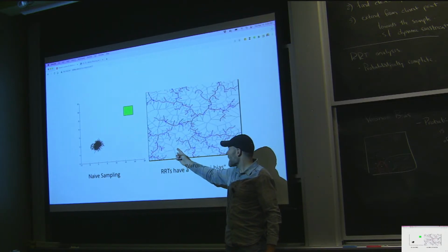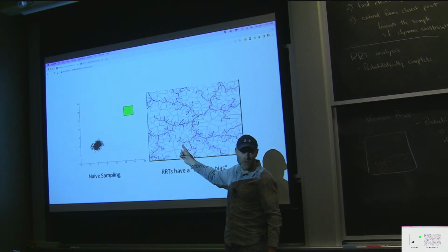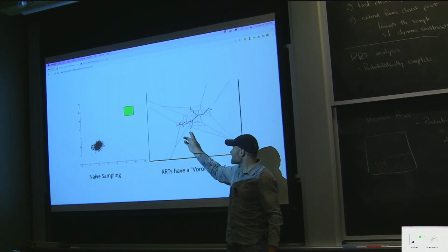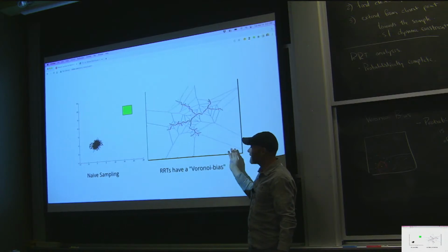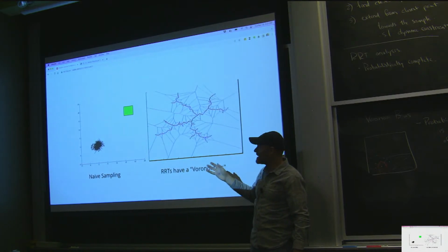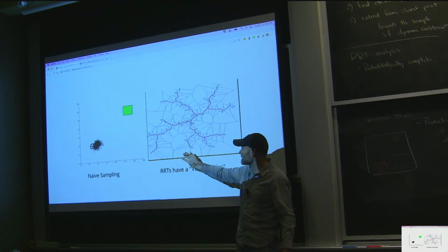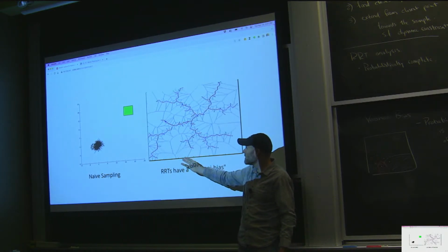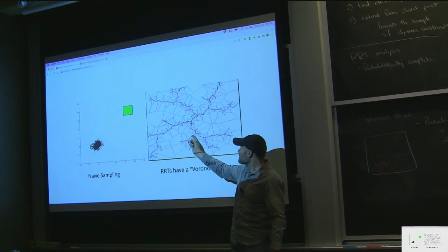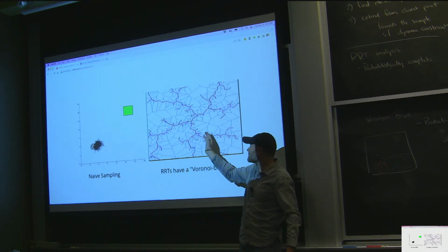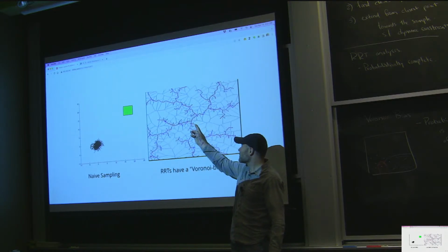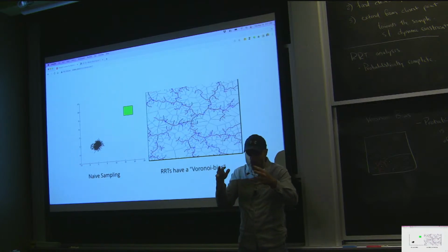And since I'm going to expand from the closest node, that means the probability of extending that edge is proportional to the volume of the Voronoi region. And it has this magical property that it will grow out, quickly making the big Voronoi regions smaller. And then at some point, when the innermost regions are large relative to the others and receive a relatively larger sampling probability, they will eventually grow in and we'll get this vine-like structure.